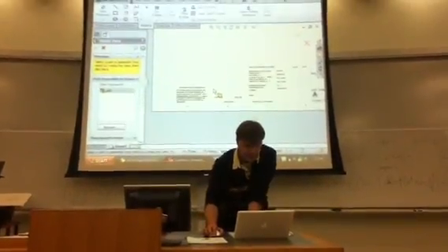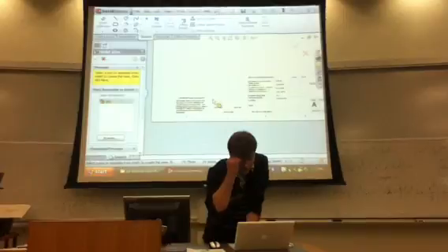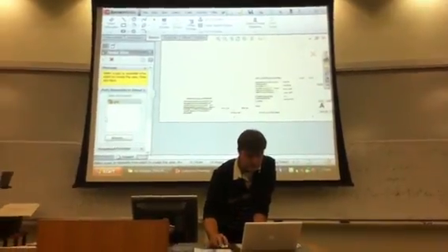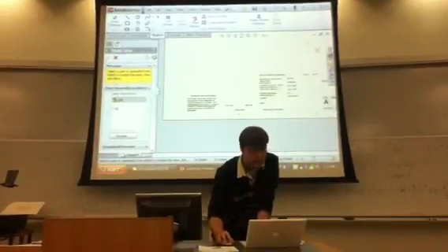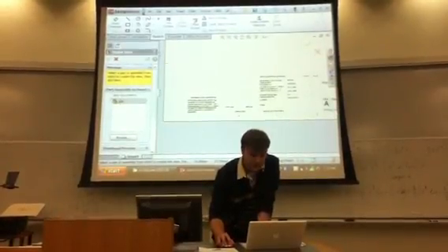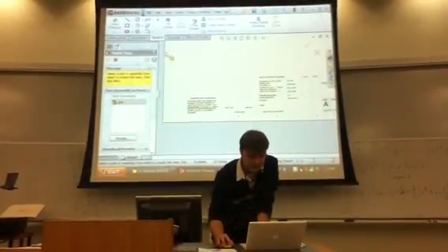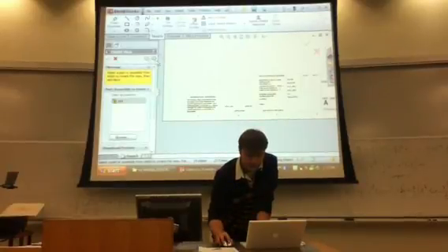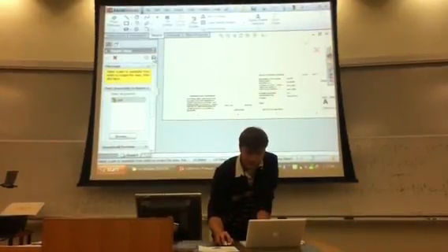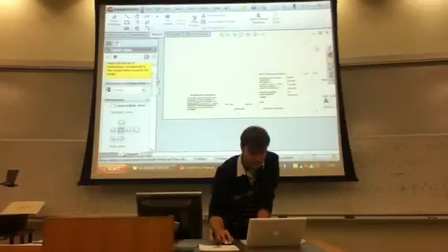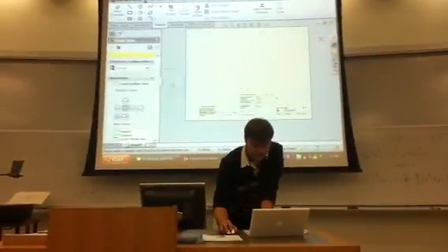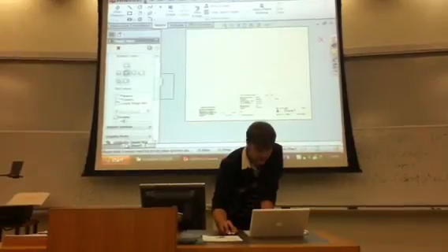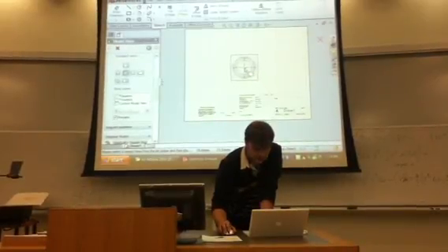As soon as you start a drawing file and you have that other SOLIDWORKS part loaded up, it'll show you that it's open, so we can make a model or we can make a drawing of that. And at the top of the side panel over here, there's a little next button. So let's press the next button. And as soon as you do that, we're going to go down here. Make sure you press preview, it's a lot easier to deal with.